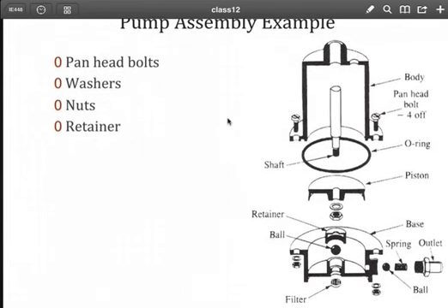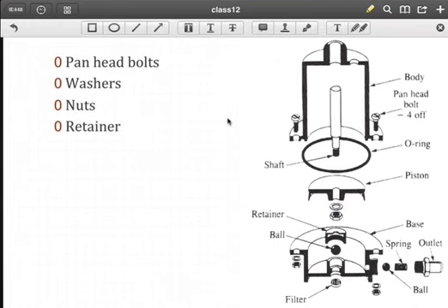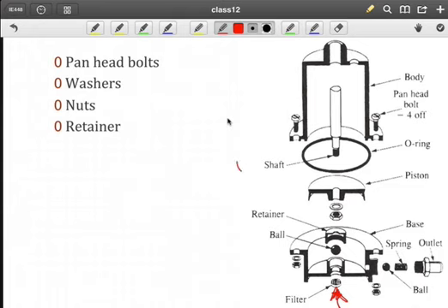If you look at the pump assembly here, we have a classical piston pump where the fluid is entering the pump at the bottom, passing through a filter, and so when the piston moves upward, the fluid here will unseat the ball, and now we have fluid moving into the chamber here, and obviously as we move the piston further up, we're going to pull in even greater volume. And then when we push the piston down, of course this ball will seat against that and essentially acts as a check valve to prevent fluid from flowing out through the bottom.